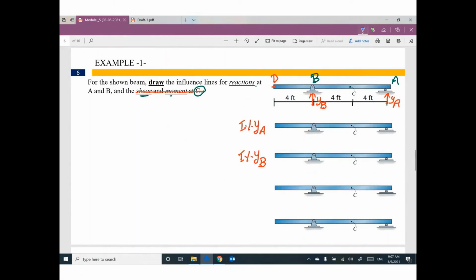So, can you tell me how can I draw influence line for YA? Yeah, move, keep the resulting deformed shape. Move what? Support A, move support A up. If you move this support up by 1, keep any other support. Do you have other supports? Yes, we have. B, keep it. So we have 2 points, one moved up and the other one as it is. Can you tell me what is the new position of this stick or this beam? I think the new shape looks like this.